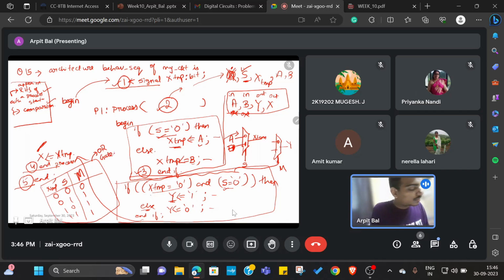Okay. So what I can do is, I have S, I will take X term, I will put an OR gate here, and that OR gate will behave as the selection line to the next mux. And whenever that is 0, I should select 1. Okay, and whenever that is 1, I should select 0. Okay, and this synthesizes our hardware.